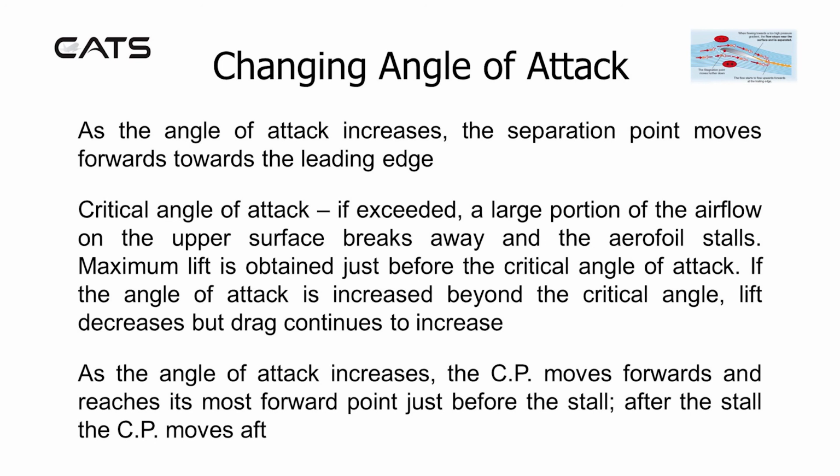Critical angle of attack. If exceeded, a large portion of the airflow on the upper surface breaks away and the aerofoil stalls. Maximum lift is obtained just before the critical angle of attack. If the angle of attack is increased beyond the critical angle, lift decreases but drag continues to increase.